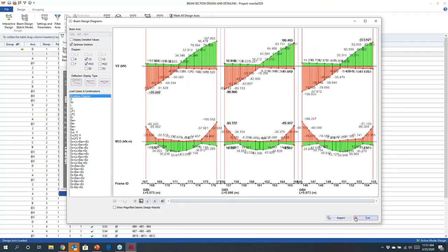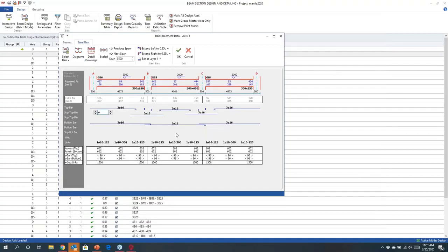Now, for the design, we will firstly apply the longitudinal bars. We will work out, based on what's actually provided, the moment capacities at each end of the beam, and then we will work out the shear design based on critical shear. So we will take the moment capacities divided by the length, obtain the critical shear, and design our link arrangements based on it.